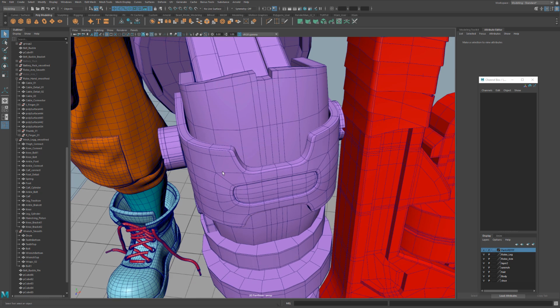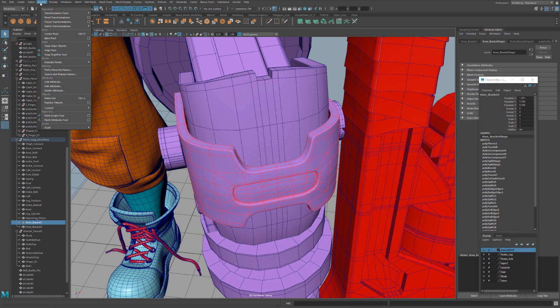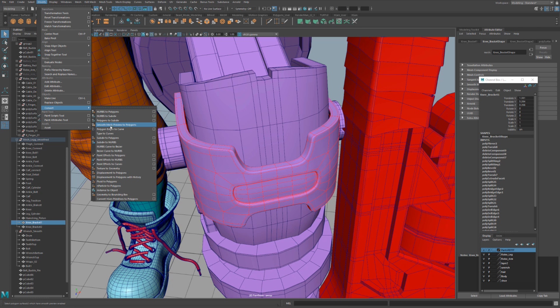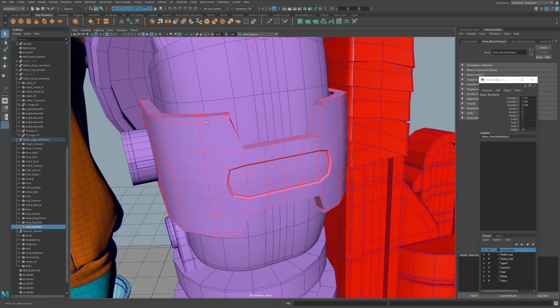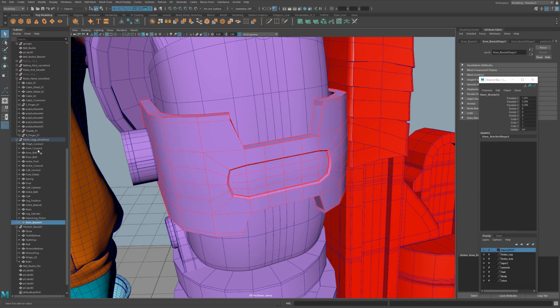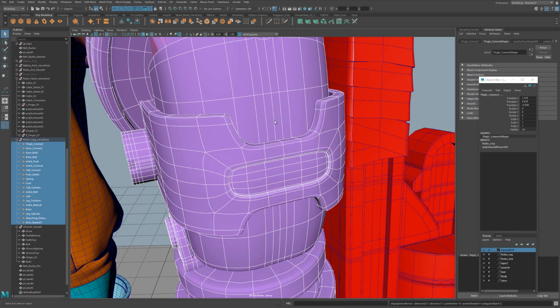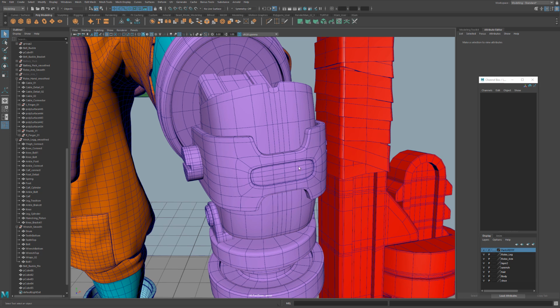One thing that you might want to do, since this is an instance, you can go in here and do modify and go to convert. And then we can take this instance to object, and that's back to a polygonal object. Now this is a polygonal object here. Looks like we have a duplicate here. We could get rid of that. And now we could just go in here and just hit 3 mode on all these. And we have a nice updated piece that we really didn't have to touch, and we were able to model the updates just using the ease of world spacing.